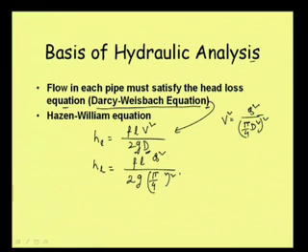So now this expression we can write as FL Q square, and another D was there, this D is already there and the other is coming from the area. So it is FL Q square, then twice G, then pi by 4 square. We can simplify this, but let it be like that, we are not worried about that expression. Then D square whole square is D to the power 4, then another D, so it is D to the power 5.